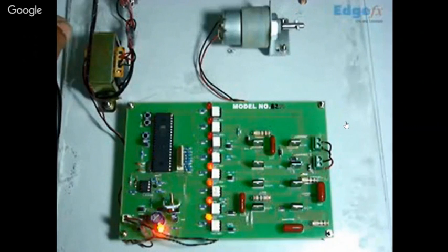There also, in FACTS devices, you can see voltage source converters are used. By changing the firing angle, you can make the exchange of real and reactive power there, based on what type of load, like a capacitor or inductor, will be connected. So is there any doubt? I think at 1 o'clock many of them have left. This is just DC I've shown you, but the same thing is possible with AC also.